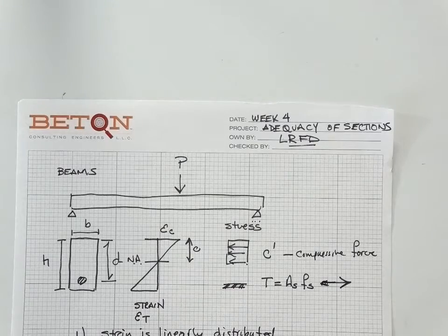So we've been talking about beams, and what we have up on the screen is a beam. The beam has a load somewhere on it that's causing it to bend down, forming a concave shape, what we call a sagging moment that causes the beam to sag. Do you remember what the other one is called if it causes the beam to mount up? It's a hogging moment, because it looks like the back of a hog. Engineers, pretty simple people.